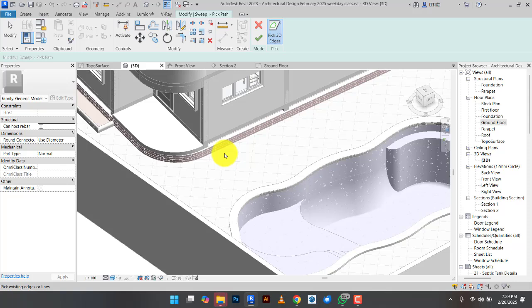Whether horizontal or vertical, you extrude. But once it curves, you sweep. Excellent. I think that will make it easier. If it's following a path, you sweep. But once it's a straight path this way, extrude. No two ways about that.